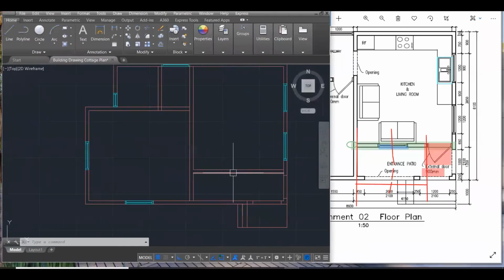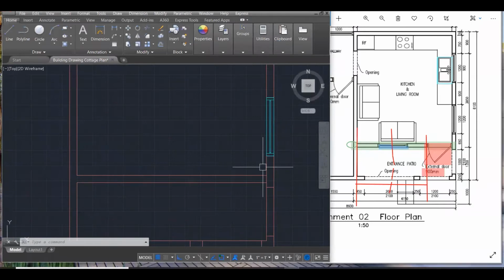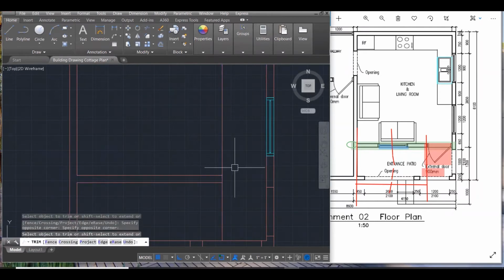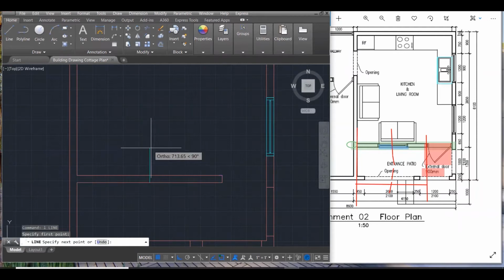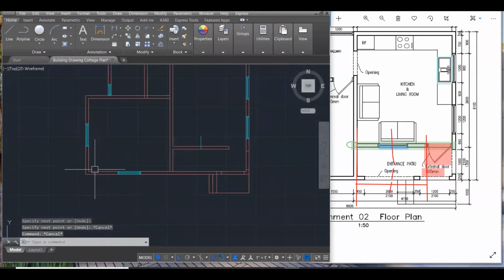That's the strategy. So the first thing is the door is a 900 door. So let's offset 900 so that we mark out where the door goes. What we can do is just trim off that as the doorway and trim off that here. And then we find the halfway line for here, right? And once we find the halfway line, we can just leave an indicator there.